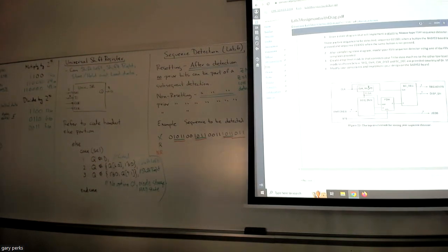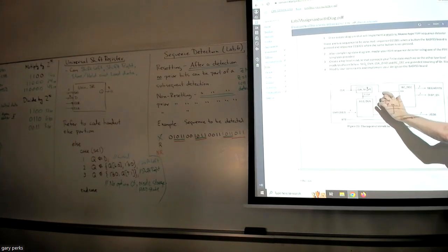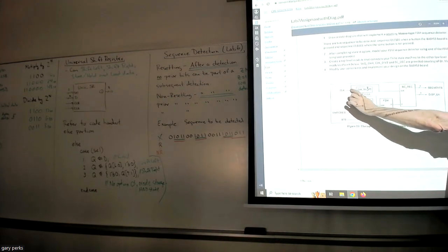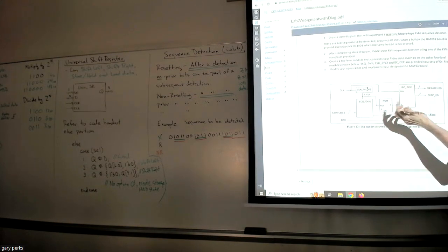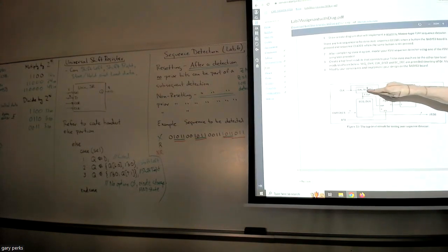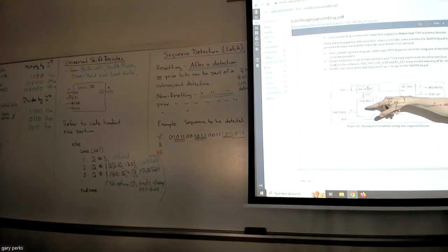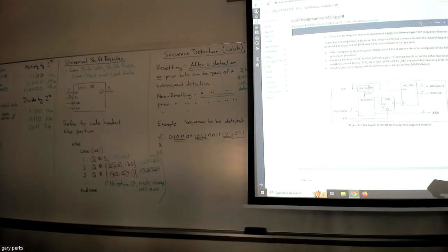But getting back to this diagram. The clock divider, like we said, is going to slow down the clock. Now notice that BC deck, this module of Dr. Mealy's, it takes the fast clock. So you see, this is the 100 megahertz, and it bypasses the clock divider because his BC deck needs the fast clock in order to work right. But the slow clock, what's coming out of the clock divider, that's what's running the sequence driver and also your FSM. So the FSM and sequence driver are operating at the slower frequency. BC deck is operating at the fast frequency.